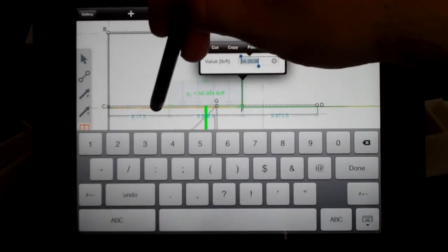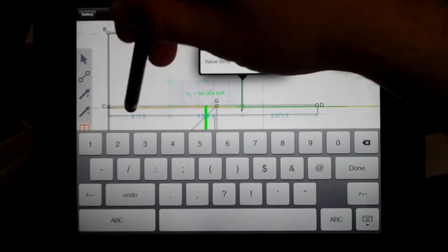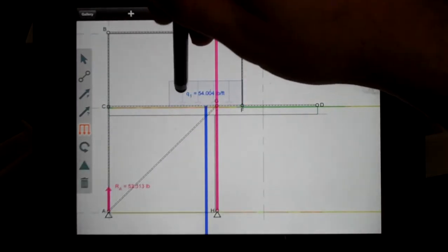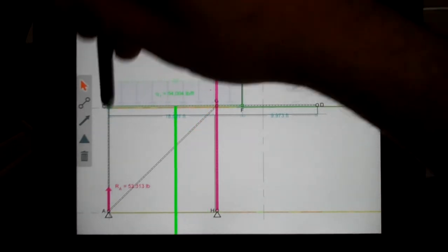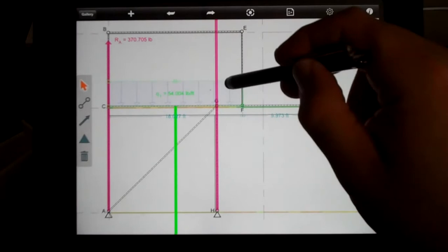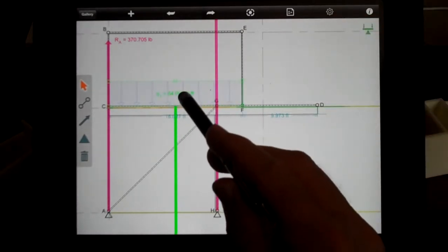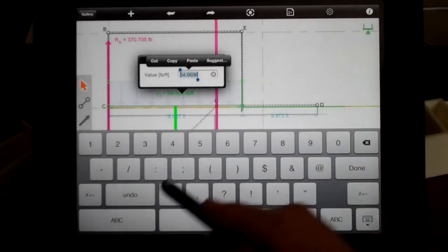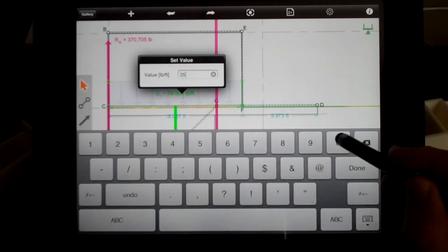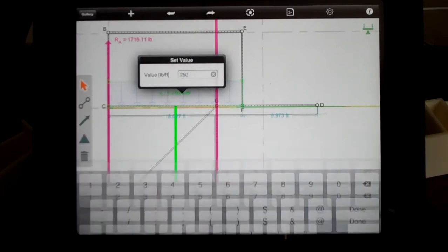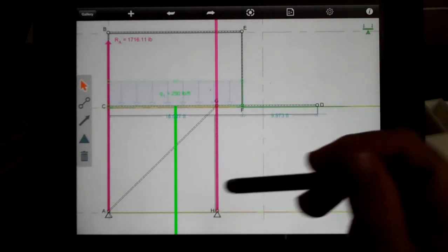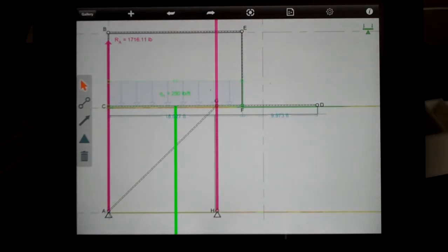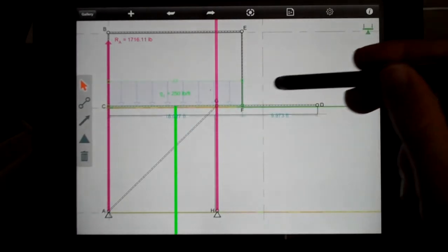And I'm going to drag that across, and then I'm going to select the lower piece and slide that distributed load all the way across the interior space. Then I'm going to select the pounds per foot mark and set that interior to 250 pounds per square foot. And of course, I'm thinking about the structure running in both ways. So maybe that is taking 10 feet in each direction, so it's a fairly large load.